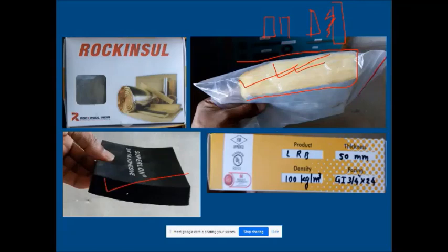This can also be a sound absorber. Sometimes we use it on hot water pipes or AC ducts; they should be covered by sound absorbing material. And mostly sound absorbing material is also a good thermal insulator. Not in all cases, but most of the time. We will discuss in detail. Suppose you have this kind of material with porosity. If the pores are connected to each other, and we have porosity on the surface also, this will act as a good sound absorber and a good thermal insulator also. But suppose the porosity is not interconnected, then this may be a good thermal insulator, but it will not act as a sound absorber.